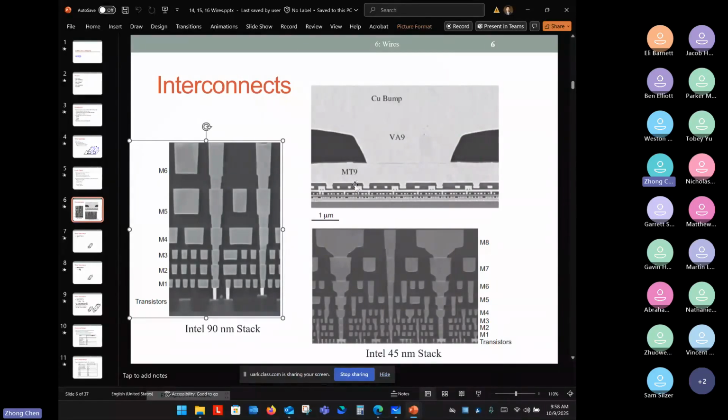That stress is going to affect the transistor threshold and some critical parameters. So you will find out that you are not allowed to place active devices underneath the bond. There's some technology that does require that.